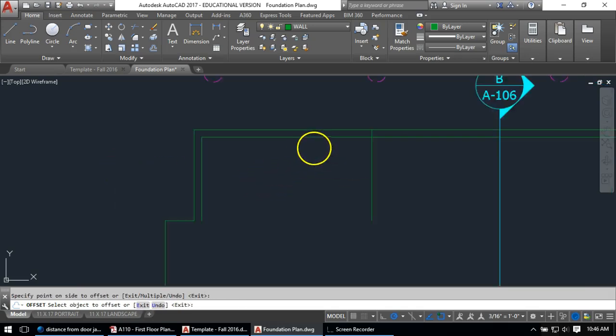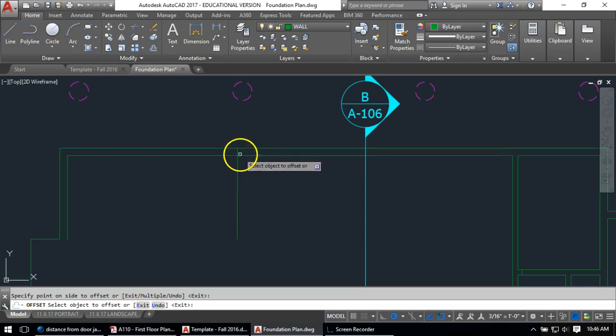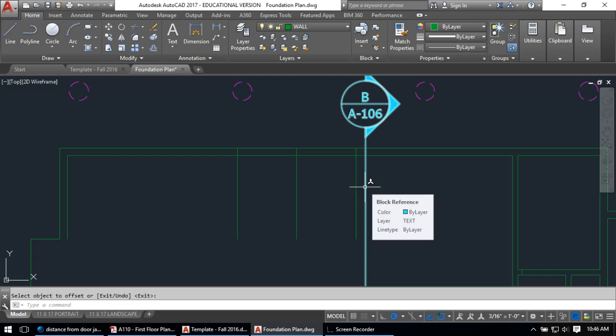over. That finds the center point of this little piece of wall that's going to define the doorway onto the deck. Then I got to go over 4 foot 1.5. That's going to find the center point of the door. But I actually need 2 of those to get the next wall. So this is this little wall that we've got going on here.